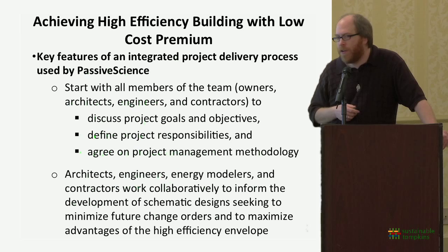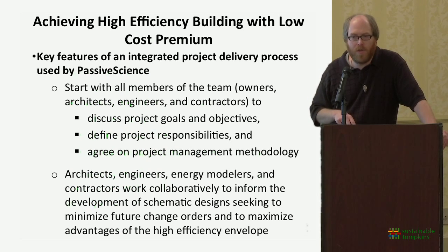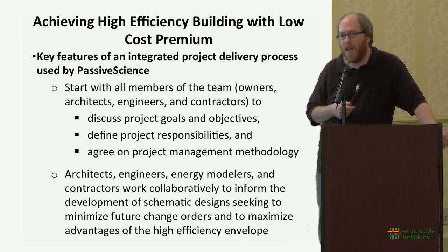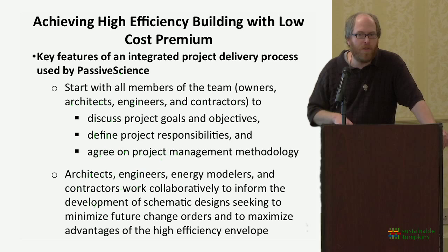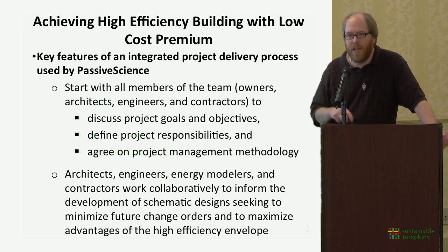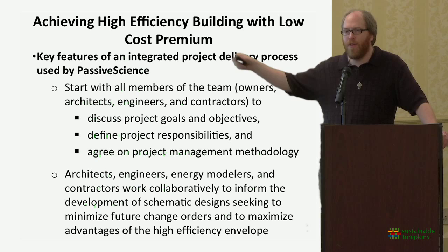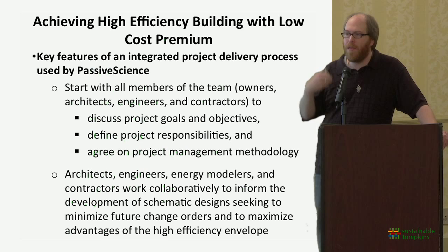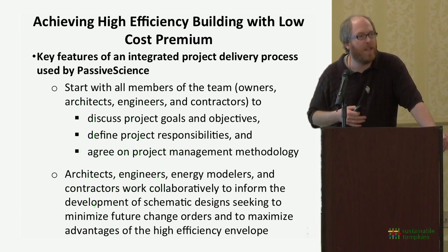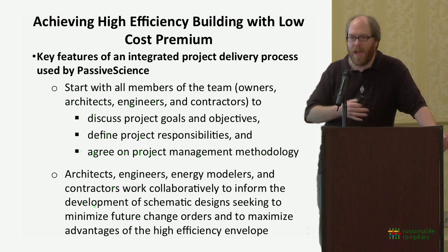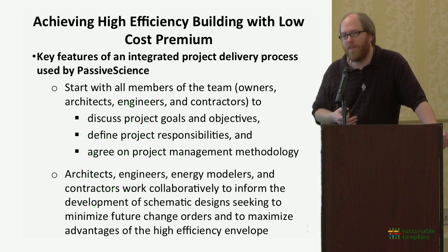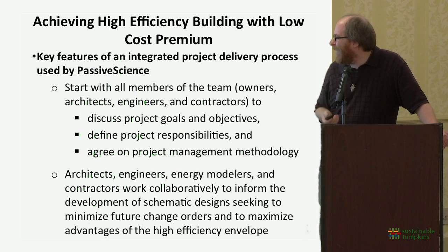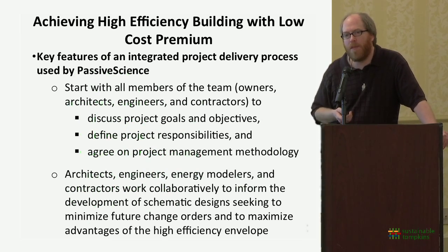Get the energy modelers started with the models as soon as possible and have everyone involved in an iterative process towards schematic design. The goal is to minimize future changes. What you want to have is as little as possible someone coming 3 or 4 steps down the process: "Oh, wait a minute, you didn't leave me enough room for this, the building wall isn't going to breathe properly and allow moisture to move. Go back and redesign this." Those change orders are where a lot of the extra cost in really high efficiency buildings come from. So the sooner you begin to integrate all of these people into the process, the better.